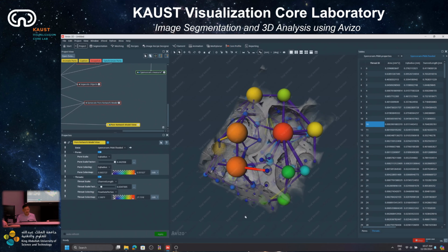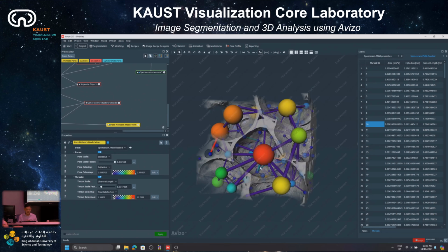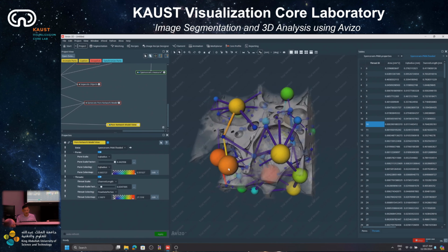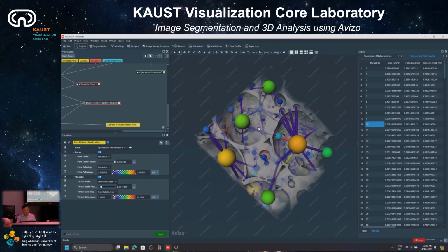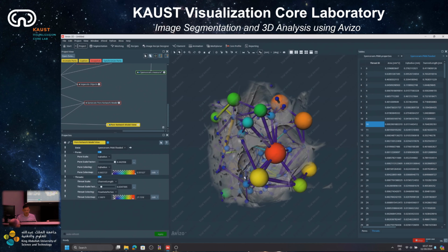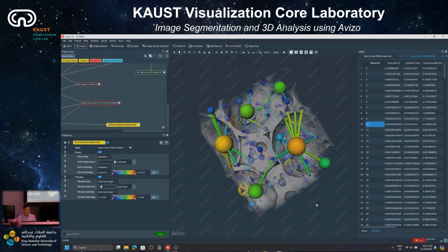First we need to segment the pore using auto thresholding, so all this pore space has been segmented. Then we select only the pores that are somehow connected, and separate them into individual pores because we want to calculate the pore network connectivity. At this point, we can look at the equivalent radius or equivalent volume of the pore as a sphere, and then calculate, for example, the flow rate or the channel length like this. So consider the throat as the length and the channel that connects two spaces.